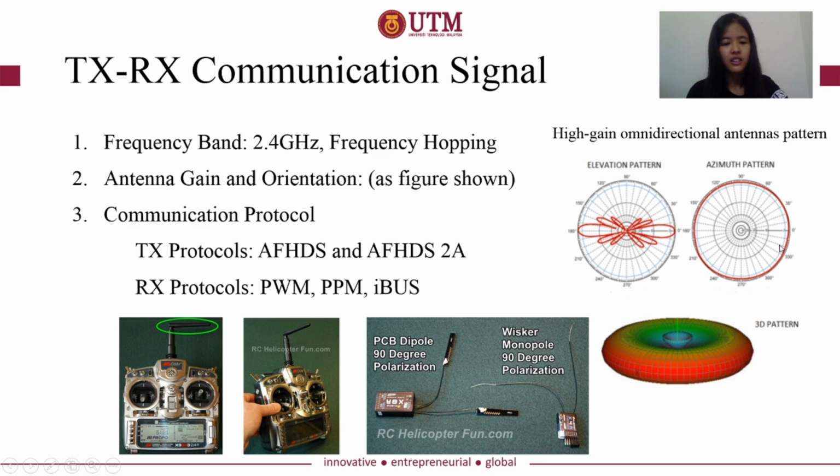Therefore the transmitter antenna orientation is recommended to be tilted horizontal, or even better, up and forward. Next is the receiver antenna orientation, where we recommend a 90-degree polarization.